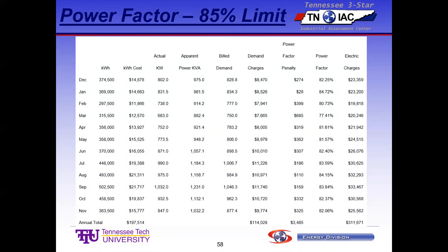From this information, you can go back and construct the power triangles and estimate how many kVAR of capacitors. We usually use like 60 or 80 bucks a kVAR as an installation cost. If you think they have to do switching, you might do 100, something like that.